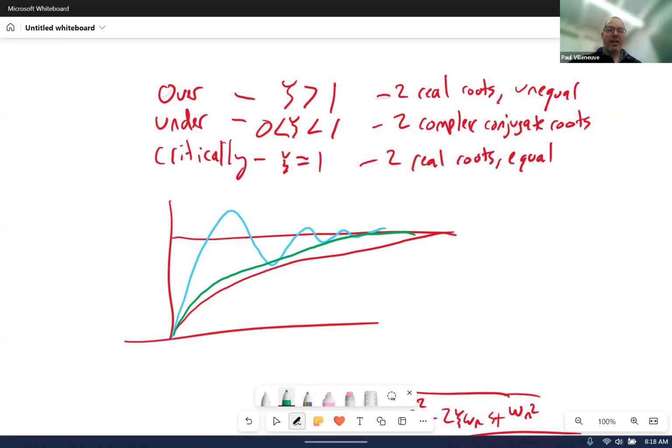The reason why we like to use an underdamped system is because if systems degrade over time in the real world, you can get some changes. Typically systems get less efficient, meaning they have higher damping because you have more resistance. So a system that you designed as critically damped would actually move to the overdamped regime, and the system would take longer to reach steady state.